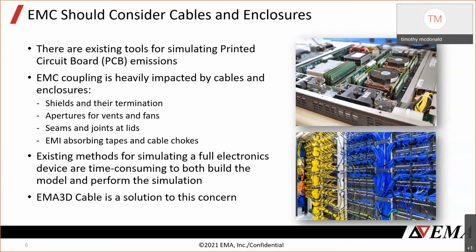The workflow that I'm going to be talking through today is much easier to put together. Instead of talking about weeks of time for an enclosure model, you can import the MCAD, mesh it with the EMA3D voxel style mesh, and you can be simulating in the same day.